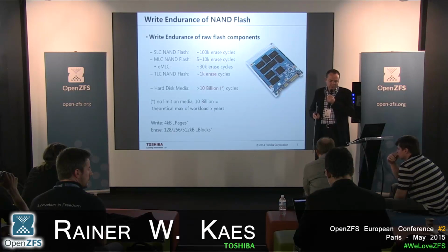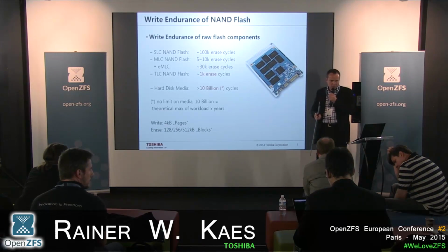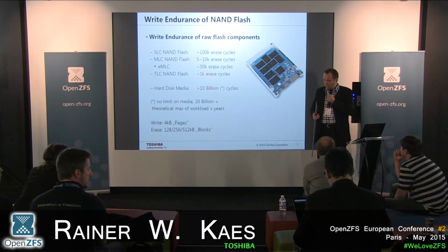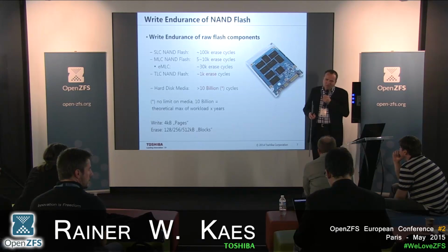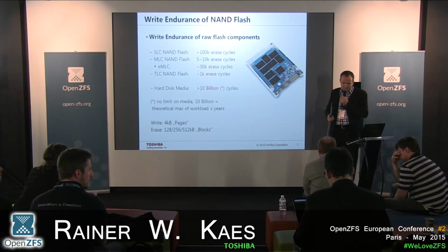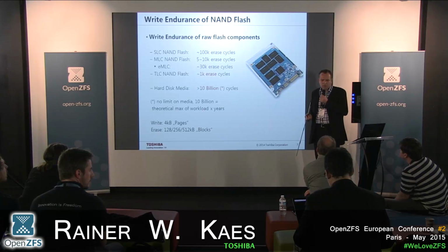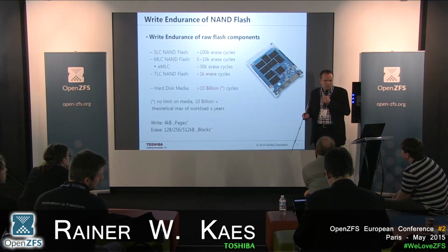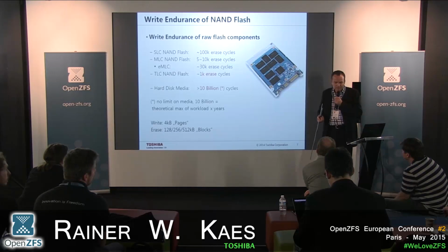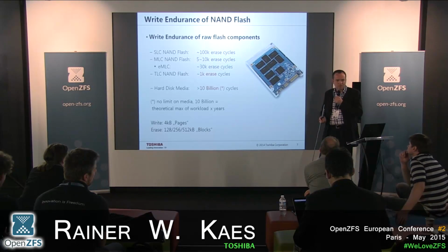It's a matter of definition. Our data book says that you unplug it, you put it in the cabinet, and it should still have the data after 3 months. It also means that if you reach the 3 months endurance point and you leave it powered, you could still use it. But we cannot give any warranty or any prediction about when it will reach a state where, for example, an unforeseen power cycle happens. So the server goes down in the evening because of a power breakdown, and your power supply does not come back until the next morning. We don't know whether the data is still there. We don't know when exactly this point is. We can only say this 3 months is the point in time.